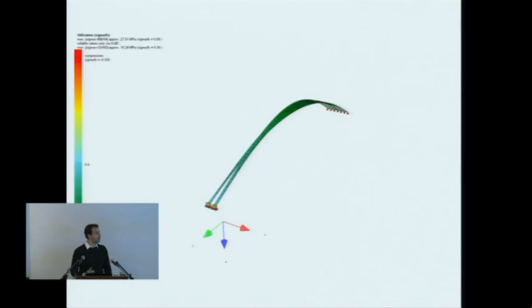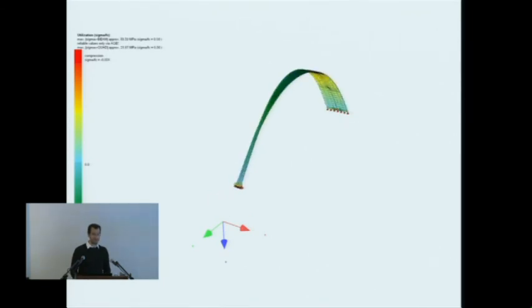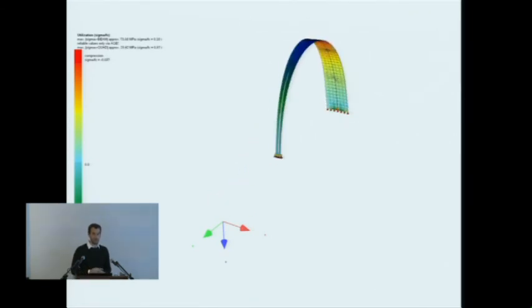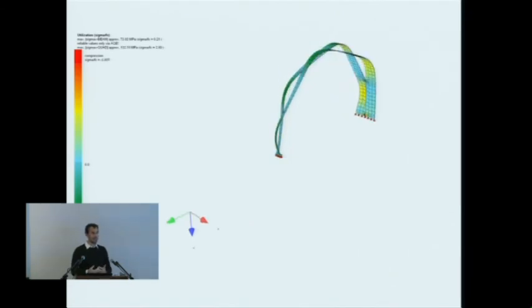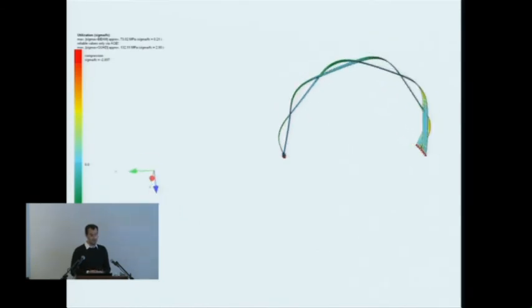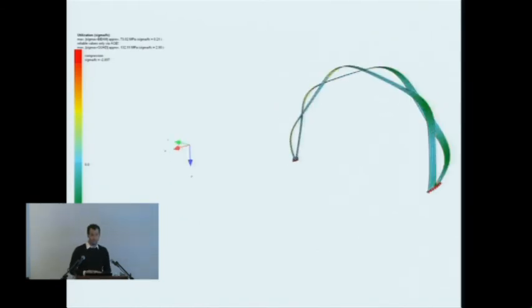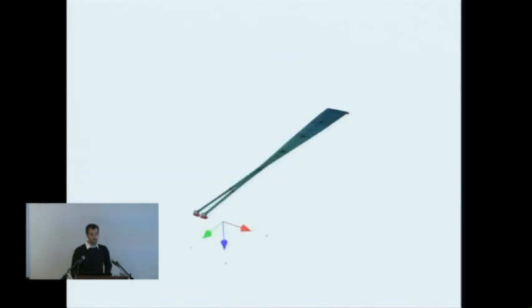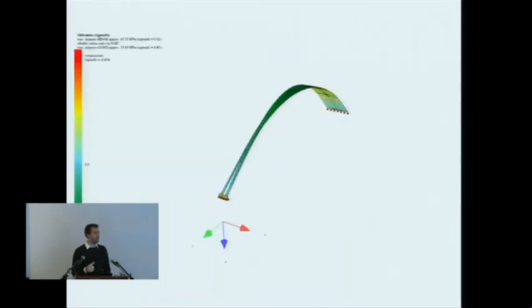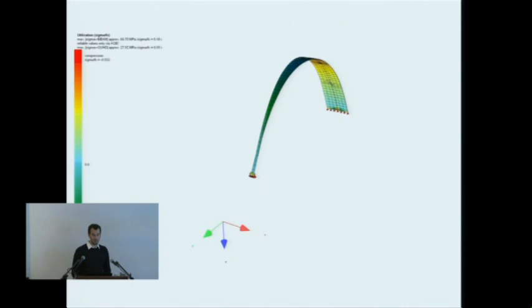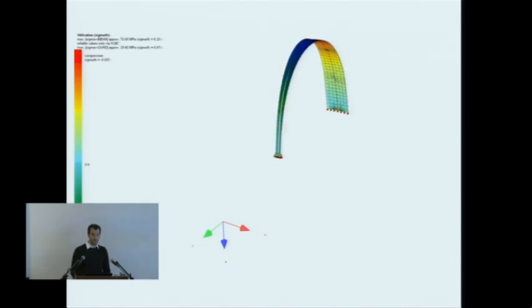So this system is actually quite simple, and it really consists only of planar strips, which you can nicely see in this material simulation here, that are subsequently connected in such a way that the elastically bent and tension regions alternate along their lengths. And this is interesting because the force that is locally stored in each bent region of the strip and maintained by the corresponding tensile region of the neighboring strip increases the structural capacity of the system.